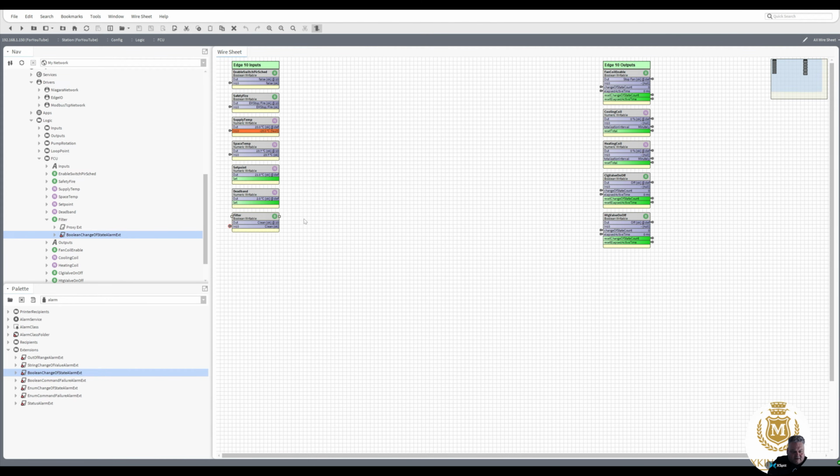I don't have a diagram to show you, but normally in offices, if we're talking offices, you've got a false ceiling, and above that ceiling you could have half a meter between the concrete roof and the ceiling, and the air handling unit normally feeds that area, and then the fan coils pull off that area.